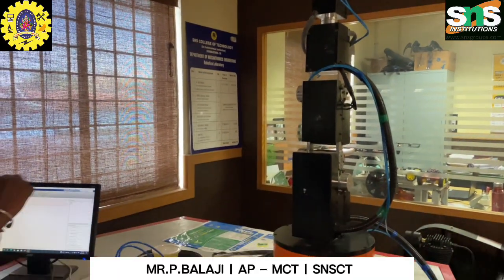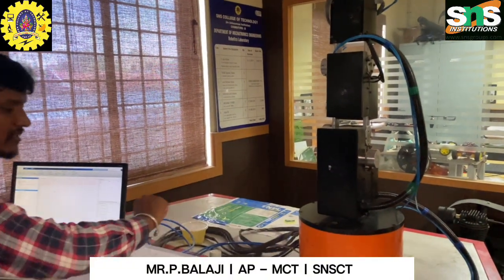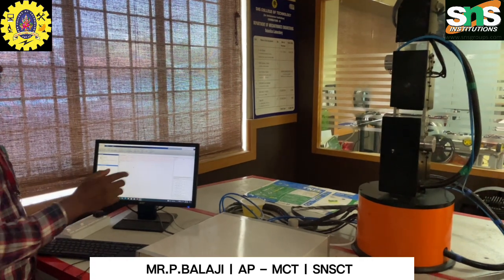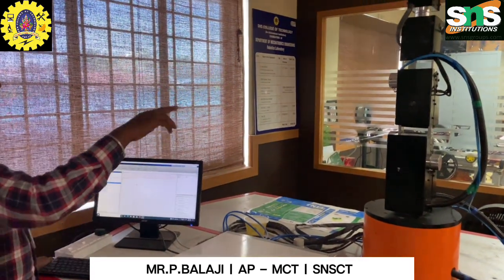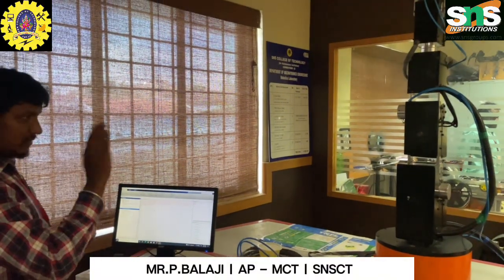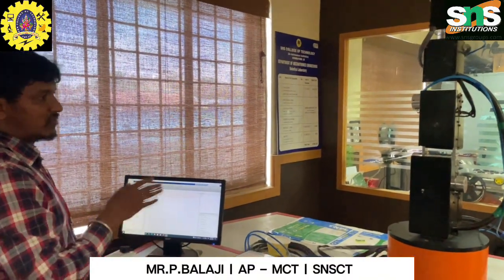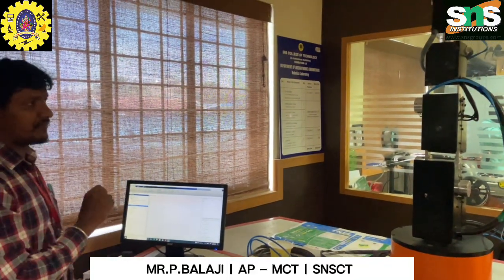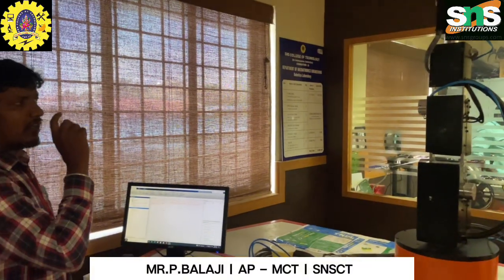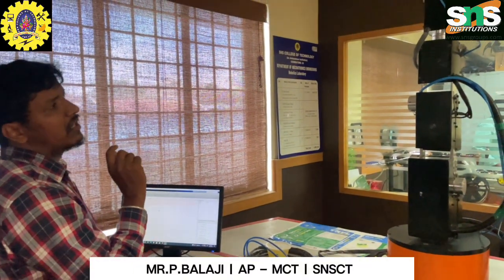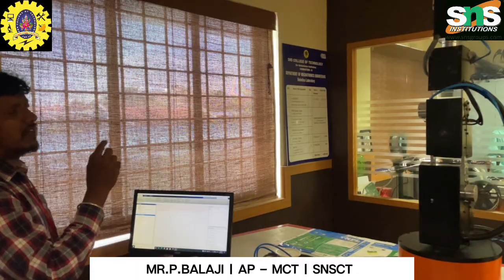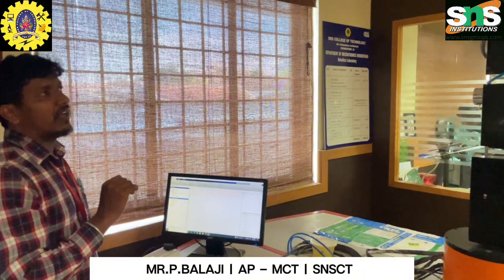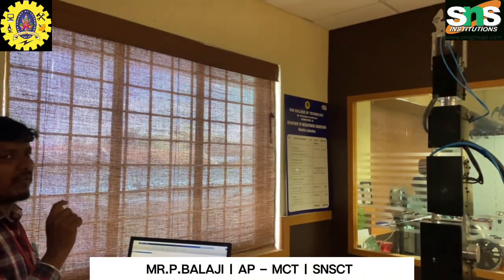Axis 1, the base axis, is used to rotate the base through the entire 360 degrees. The second and third axes are used to control the actuator for up and down motion, and we can control them up to a 90 degree angle. The fourth axis controls its actuator using a stepper motor, and with the stepper port we can control the full 360 degrees. The fifth axis controls the gripper using a 0 or 1 command.